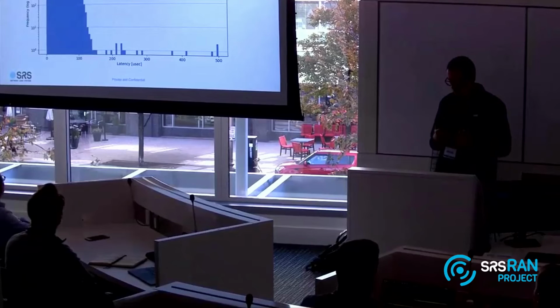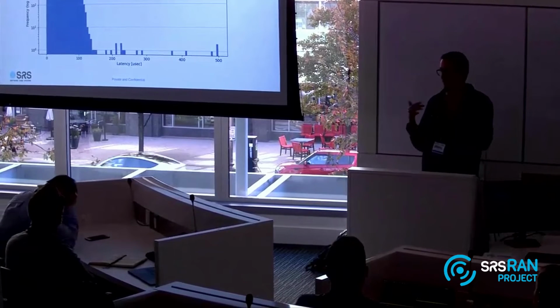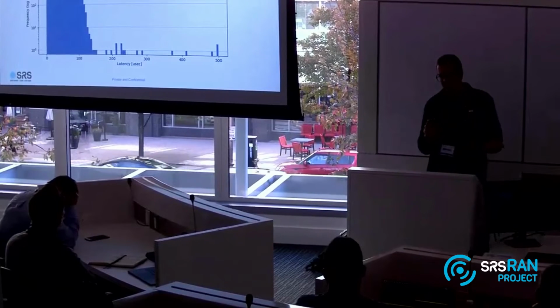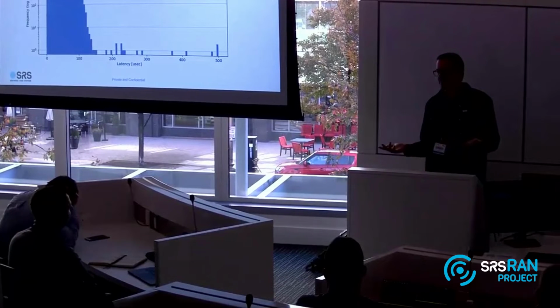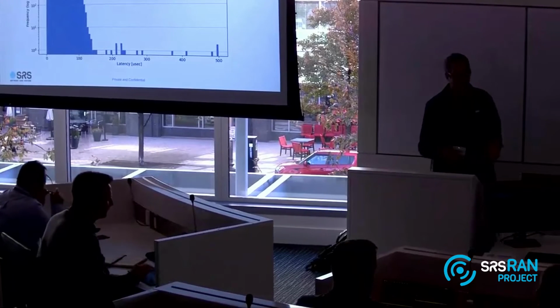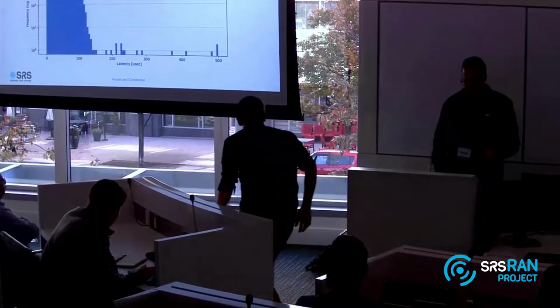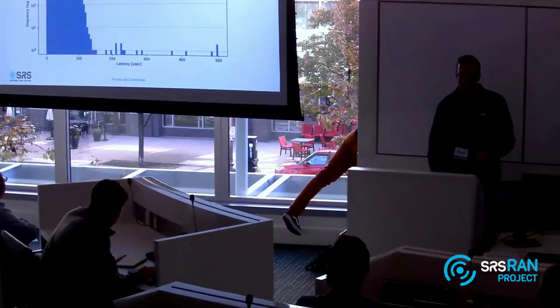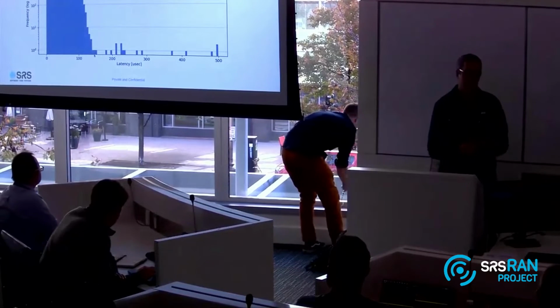Is this a lot or not? Well, you run this task 2,000 times per second because you run this task on every slot. So if every 10 seconds you are missing one deadline, is it critical for you or not? That's up to the application. In R&D or if you are doing experimentation, maybe it's not critical, and maybe it's okay if you set the boundary even here and you see 5, 10 lates per second, 5, 10 retransmissions per second.